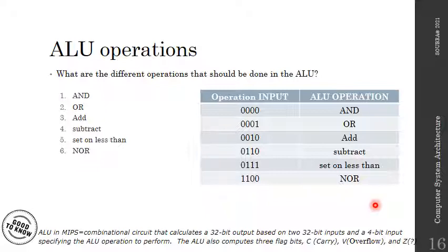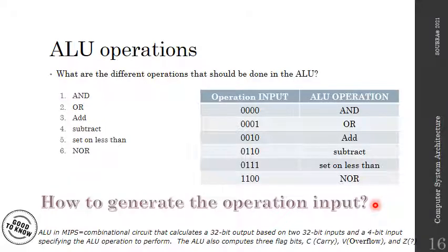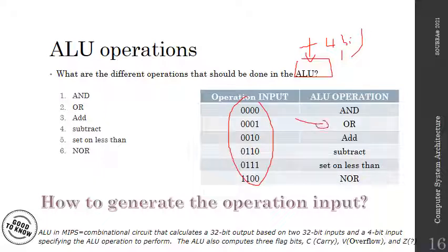All right. Now the big question, going back to what I said earlier. Here's my ALU, and apparently the control signal of my ALU has 4 bits, and the 4 bits are encoded in that way to know which operation is happening in the ALU. Now I'm going to create a control unit for my ALU. So why bother? I'm going to have an ALU control unit for a reason, because as I said earlier in today's lecture, I have 3 types of instructions. So for each type of instruction, I will need an operation.